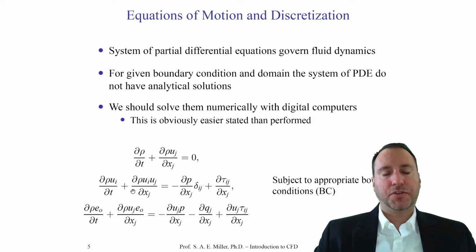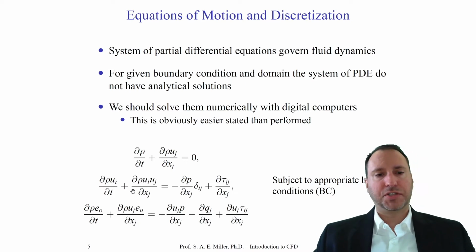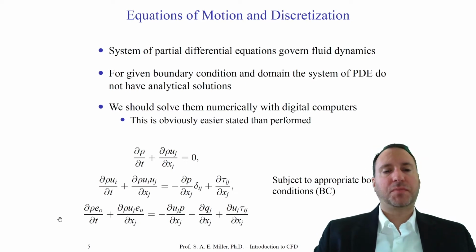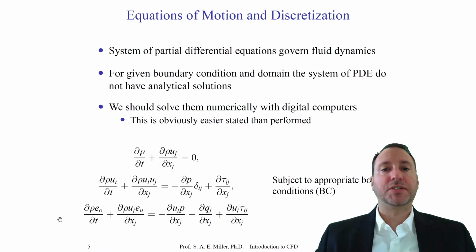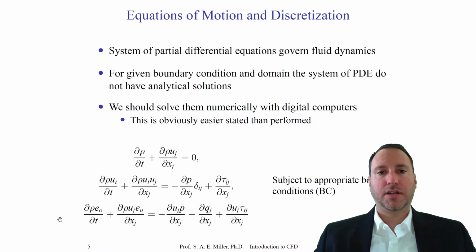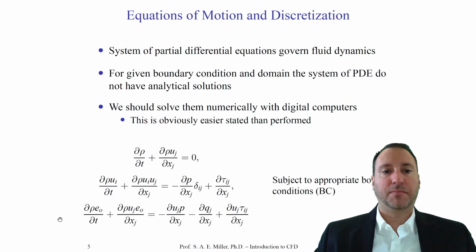Let's look at i equals 2, this y direction conservation of momentum equation. The same rules apply to the energy equation for expanding the terms. We'll look at most equations in this class in the index or Einstein notation. So please pay special attention to these rules because they'll be used throughout the class. And they're used predominantly in the research, industrial, and government communities of computational fluid dynamics. You'll be expected to see these equations and understand how they're expanded and what they physically mean.